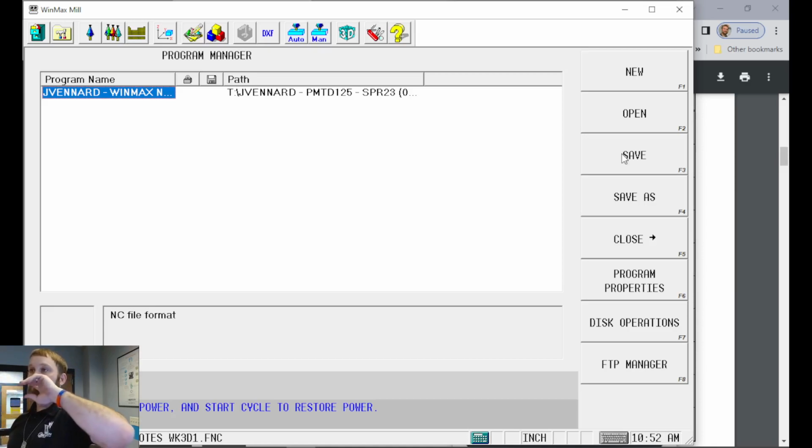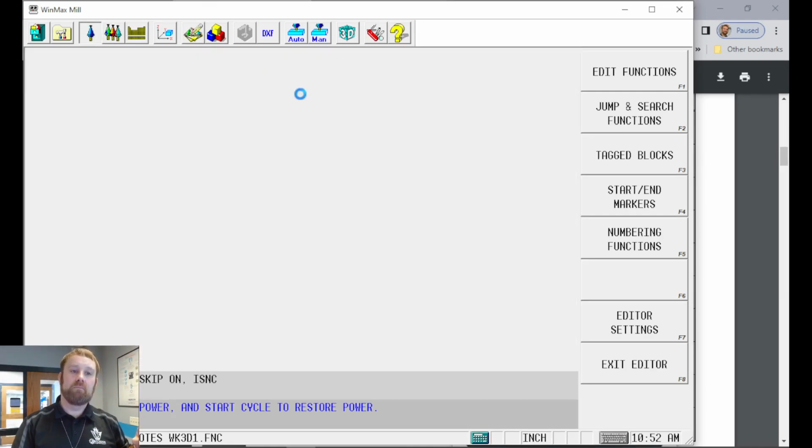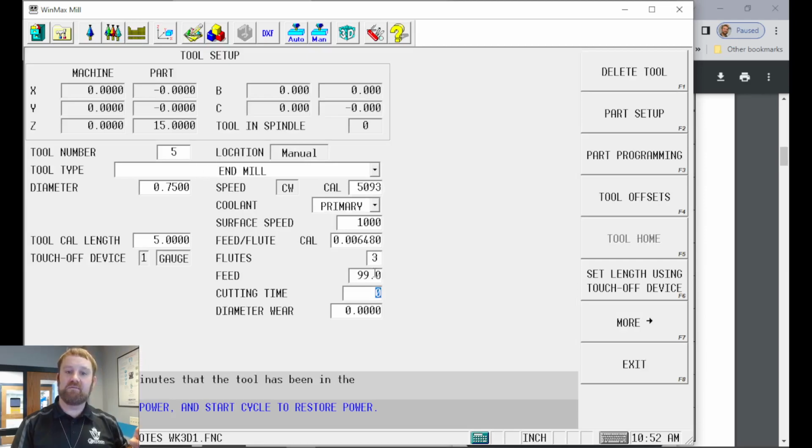You guys all right? Yeah, my feed per flute for number 5 was slightly different. Okay. What was it? It's 0.006479 instead of 6. Is the feed rate 99? Yeah. Is RPM 5093? Yeah. You're good. It rounded this a little different, is that what you're saying? Yeah. Your diameter is good, right? 0.75? Let me look at it. We're going to go back to the input screen.